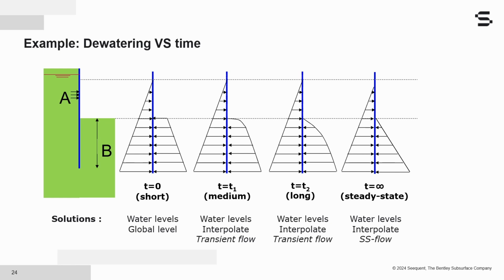These are the two extremes, and of course, what happens in between is, once we do a quick excavation, near the excavation bottom we see that the pore pressures will go to 0 at the excavation bottom, and they will have a transition to the hydrostatic pore pressure, which was there before we did the excavation, which is here. And if we wait a bit longer, to go to t equal to t2, then of course the influence zone will become larger because the water has time to react and to flow out of the soil body. And finally, after we reach an equilibrium situation, in which we see that the water table on the active side of the excavation has lowered a bit, as you can see here, then on the passive side, we do have a nice pore water pressure distribution, which is shown also here.